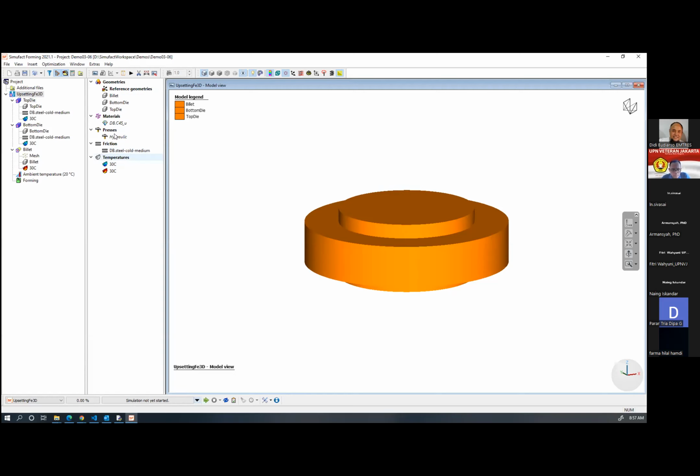There is a question whether the temperature can change depending on time. Yes, temperature can change depending on time. So even though it is a cold forming process, the adiabatic heating, that is mechanical energy converting into heat, can also be simulated in this analysis. So let me run this analysis. Once the analysis is done, even though I gave my temperature as 30, you can see there will be a slight increase in the temperature in the core region, that is in the center of the workpiece. Okay, I'll show that once.